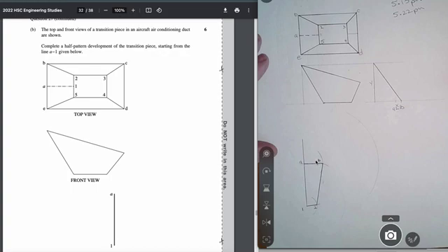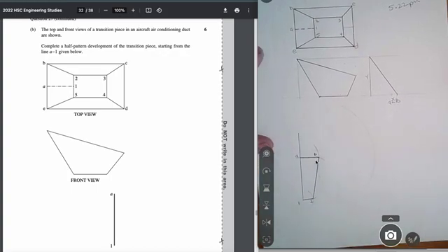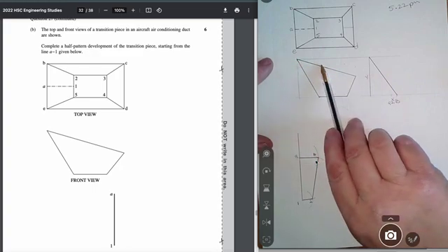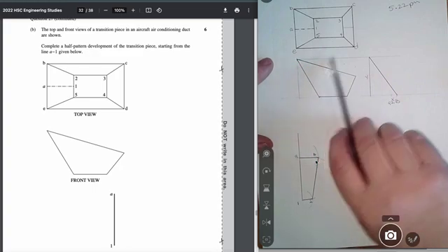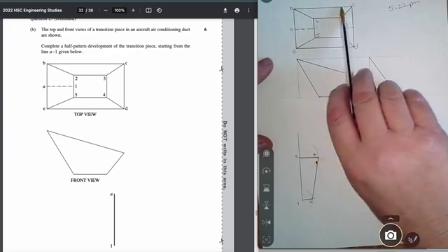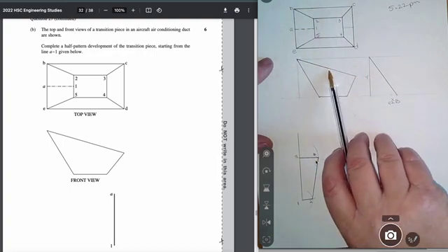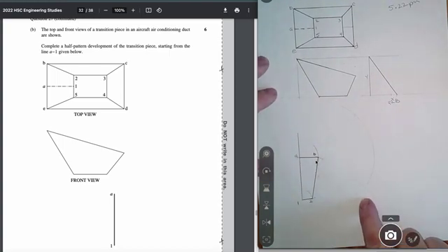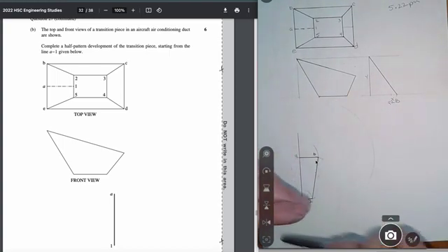I made a mistake. Look, can you see how easy that actually happens? See, this is coming down on a slope. That's not true length. Okay, so while I was going, oh, look, it's horizontal. It's not here. So it's not a true length. So this line is out. Cool, glad I discovered that one.